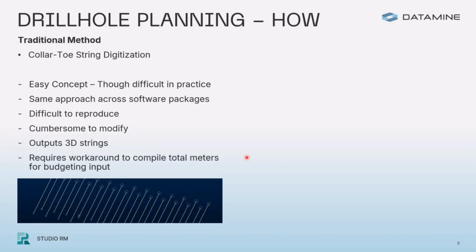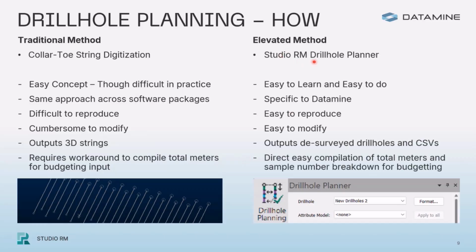So we have an elevated method. With the Drillhole Planner tool, it's easy to learn and easy to do, so that easy part is retained. This particular tool is specific to Datamine Studio RM. And the nice thing about it is it's easy to reproduce from user to user and also easy to modify if you make a mistake or if you change your mind down the road. And it outputs the survey drill holes as well as CSVs for easy computation and accounting purposes later on.